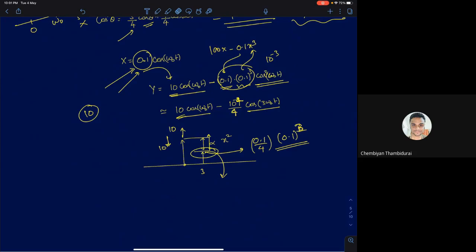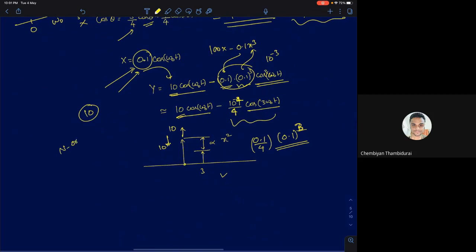So if you reduce your signal level, you will see a significant reduction in the harmonic terms. So it's a very simple result. If you have an nth order harmonic, then if you reduce your input signal amplitude by, let's say, 10 times, by what power will your nth harmonic go down?